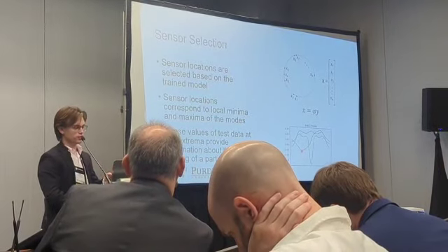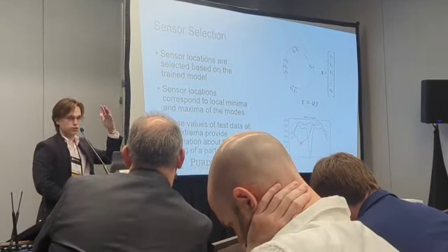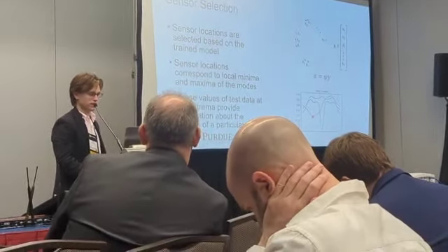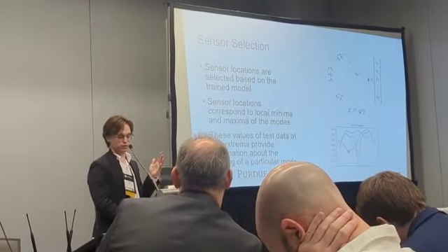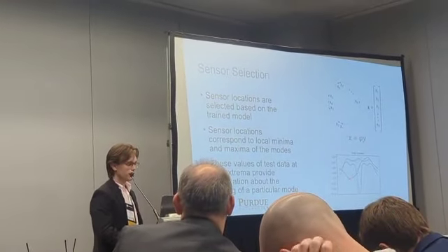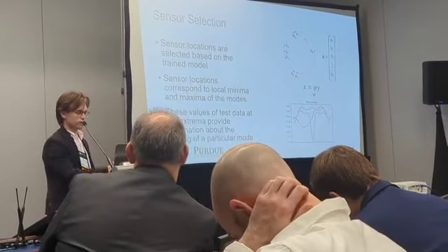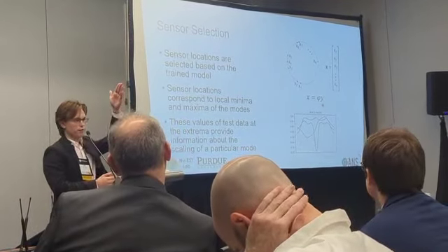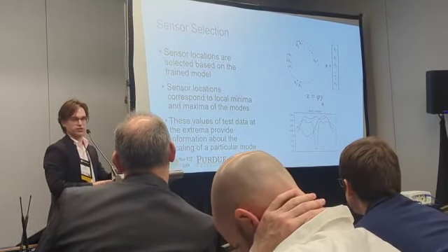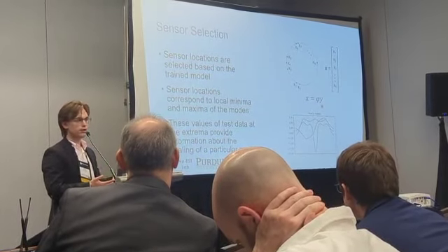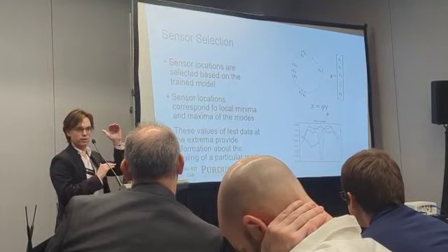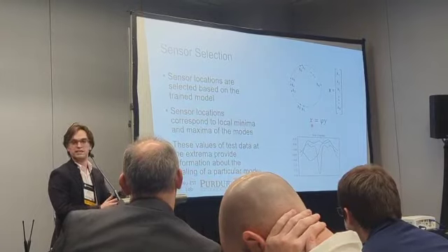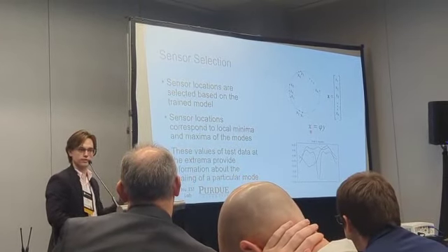So we place our sensors sequentially. We put 2 sensors in for the first mode, 2 for the second, 2 for the third, working our way down as the modes decrease in importance. And we can develop a list of likely useful sensor locations. We can then turn that information into this matrix right here, phi. All this does is take a column vector y containing however long our input vector is. Say that surface of the cylinder had 200 simulated points around it. That y vector is going to be 200 dimensions long. This just takes it, masks it, and turns it into however many sensors long vector we have. That could be 10 or 15 or something like that.